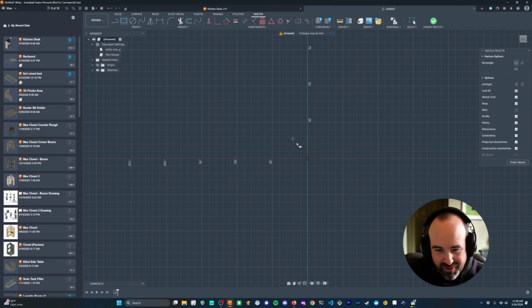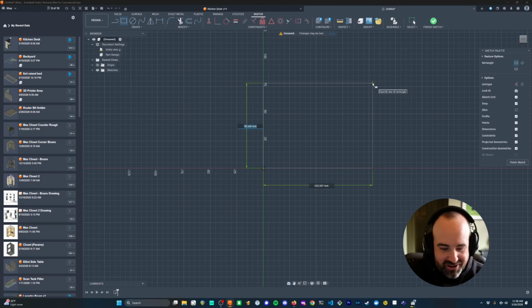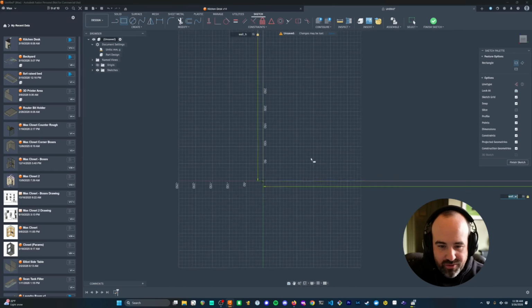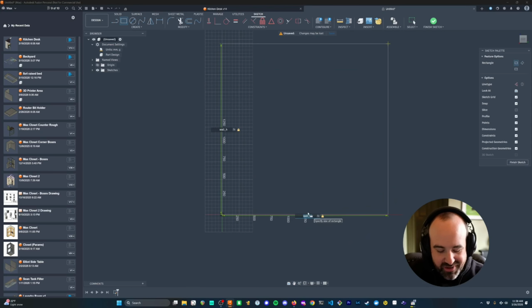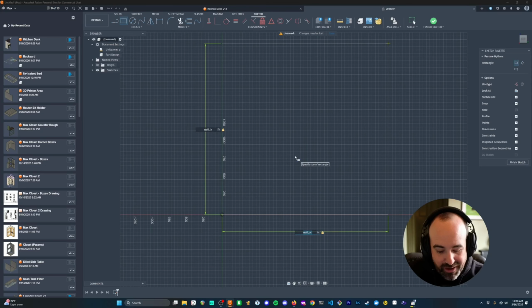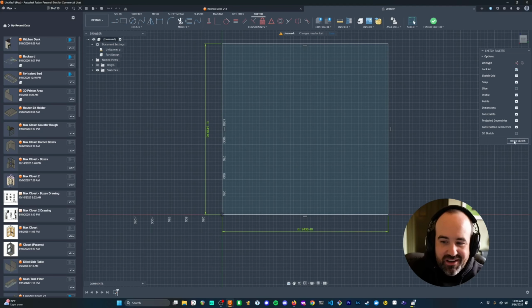And I'm not really being particular about what plane. It's kind of just like whatever plane I pick, that's how I start my drawing. So wall height, wall width as the 2 constraints. And so now you can see here, my walls aren't going to change, but now they're defined by that parameter I set, which is really nice.